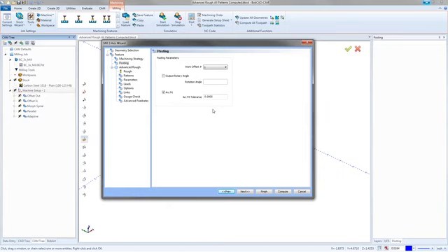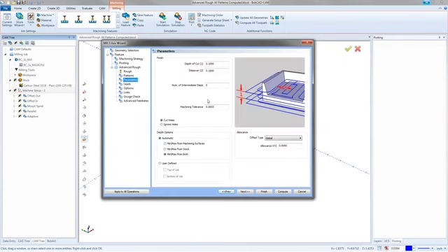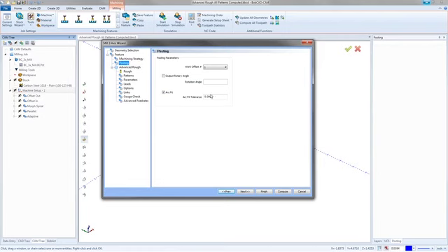The only time you'd really change this is if the arcs were not good enough, if they weren't clean enough when you were creating them. Really, the arc fit tolerance, the way I set it up, is if I go to the parameters page on my 3-axis right here and I have my machining tolerance, if I was to drop this to 1/10, I'd also go back and do the posting tab set to 1/10 as well, just to keep everything the same. That way I've got all the same tolerances on everything.